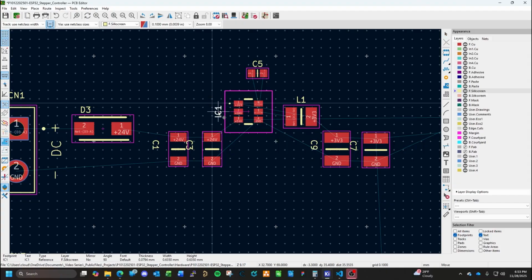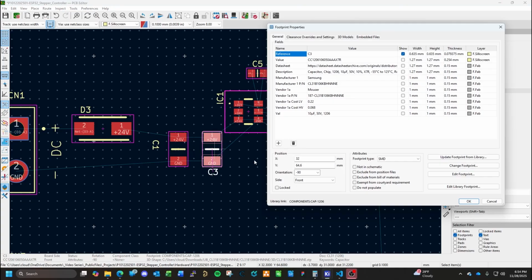I don't know if anybody recalls, but one of the typical nomenclatures in PCB layout, especially with your designators or any general text like that, you typically want to have it set up to read left to right, or bottom to top, and stay consistent as you place parts on the board. So we're going to set this guy right here. We're going to punch you in by the numbers.